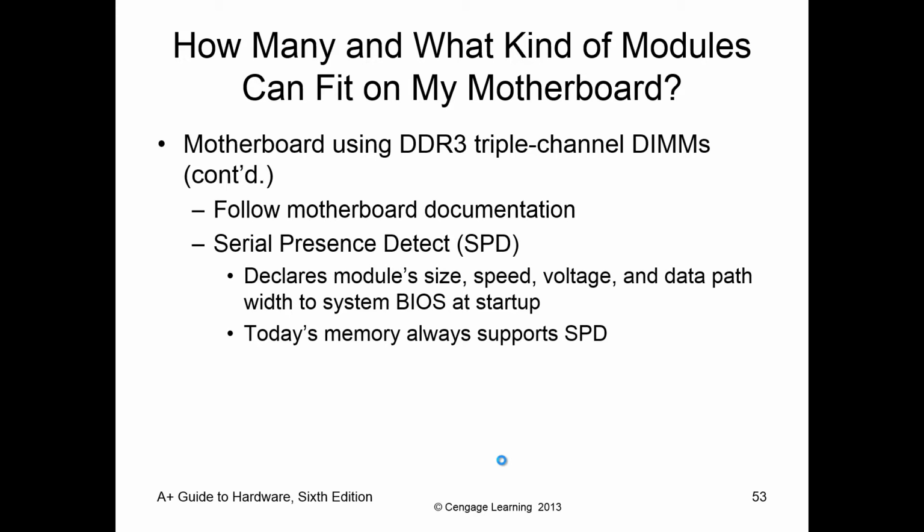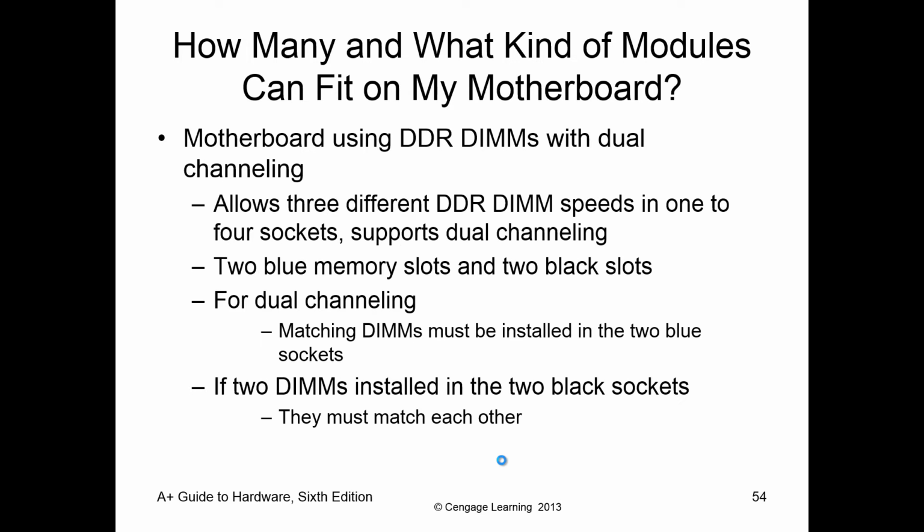If your motherboard does support tri-channel, you want to make sure that you're getting 3 memory modules that are the same speed. Realistically, if you get tri-channel memory, you can go online and buy it specifically, and the packaging will say tri-channel, and that will be 3 identical memory modules. While you do not have to use 3 identical memory modules, best practice is to get 3 matching ones. Same thing with dual channel. If it's dual channel, you want to get dual packaged memory. Again, that's just 2 memory modules that are identical.